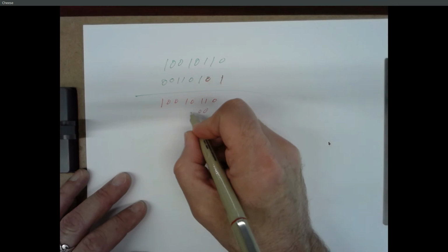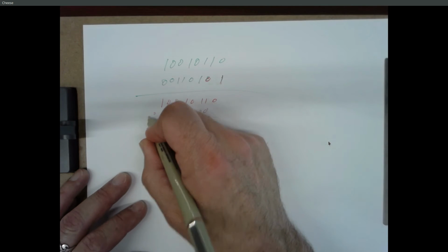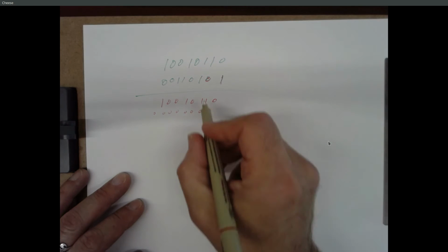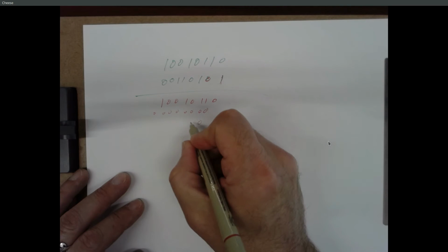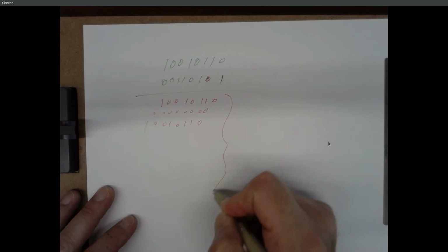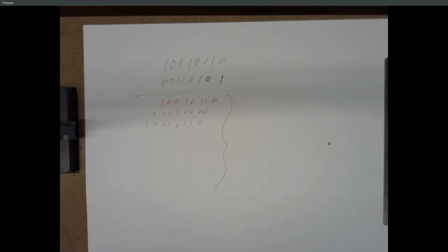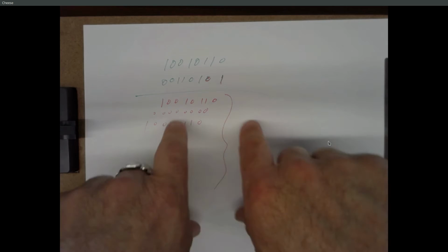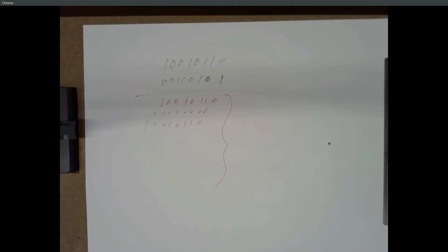Well, that's pretty easy too. You're just going to get 0. There's another 1 I got to multiply by. Is that a problem? No, I just get the original number. So getting these partial products is really fast. It's either 0 or it's the number that you're multiplying. And all your work comes in doing this addition. So a lot of research in fast multiplication comes down to doing fast addition.